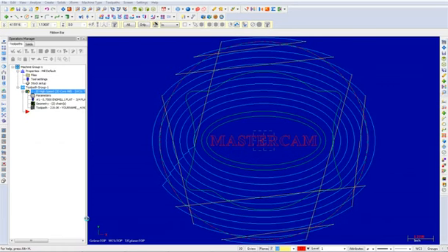In this video, we will use a 2D high-speed dynamic core mill. In this step, you will machine the outside profile using 2D high-speed dynamic core mill toolpath. Dynamic core mill machines the open pocket shapes or standing core shapes using the outmost chain as the stock boundary. The tool moves freely outside of this area. The inner chain defines the limit of the toolpath.